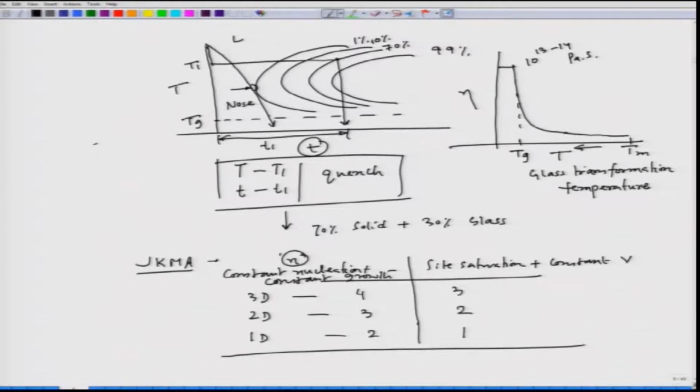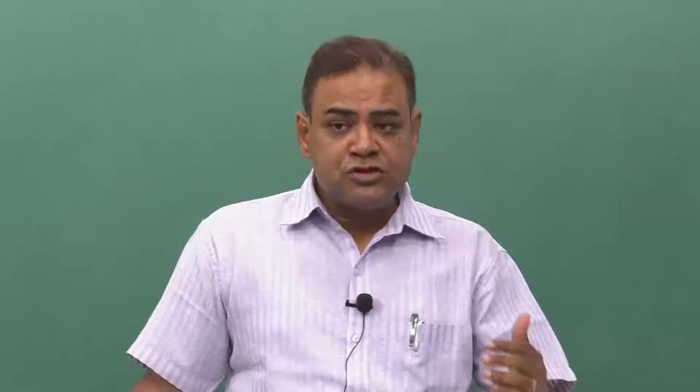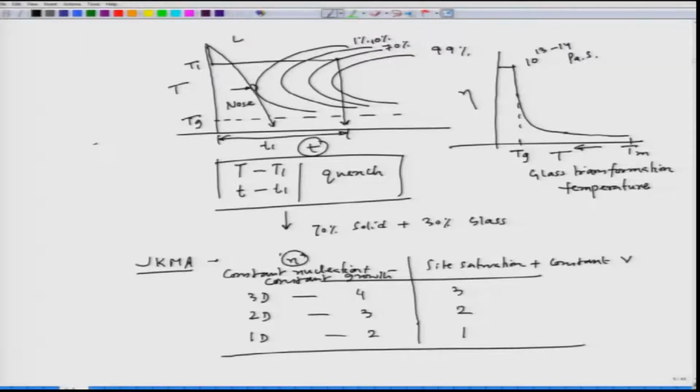But interestingly, we are only talking about the isothermal transformation diagram, which is TTT. In our next phase, we will also talk about another diagram which is also very critical from the point of view of heat treatment. For example, here we have decided this heat treatment cycle in the isothermal way. Everywhere I am quenching to a certain temperature, holding for a certain time, and then quenching again. So, we are doing those transformations isothermally.